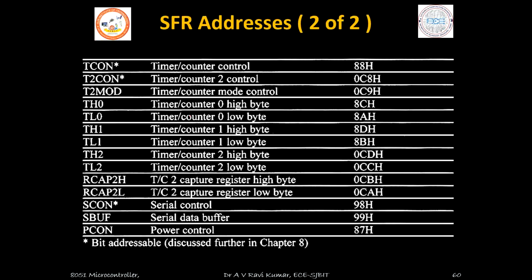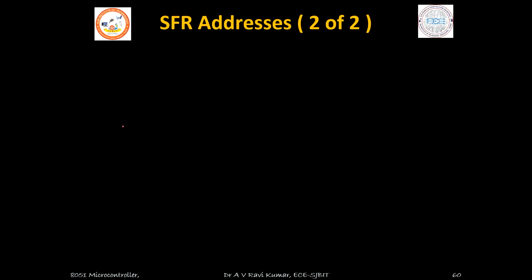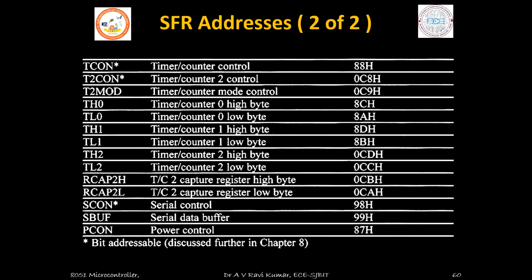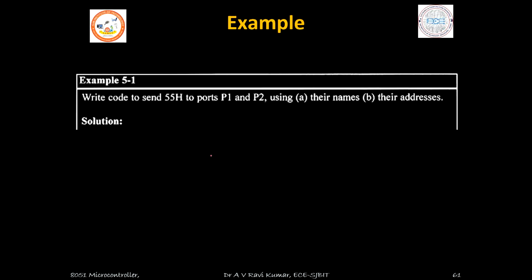Port 1 is at 90H, and port 2 is at A0H. We should remember that, so that I can copy the value 55H into port 1 and port 2.